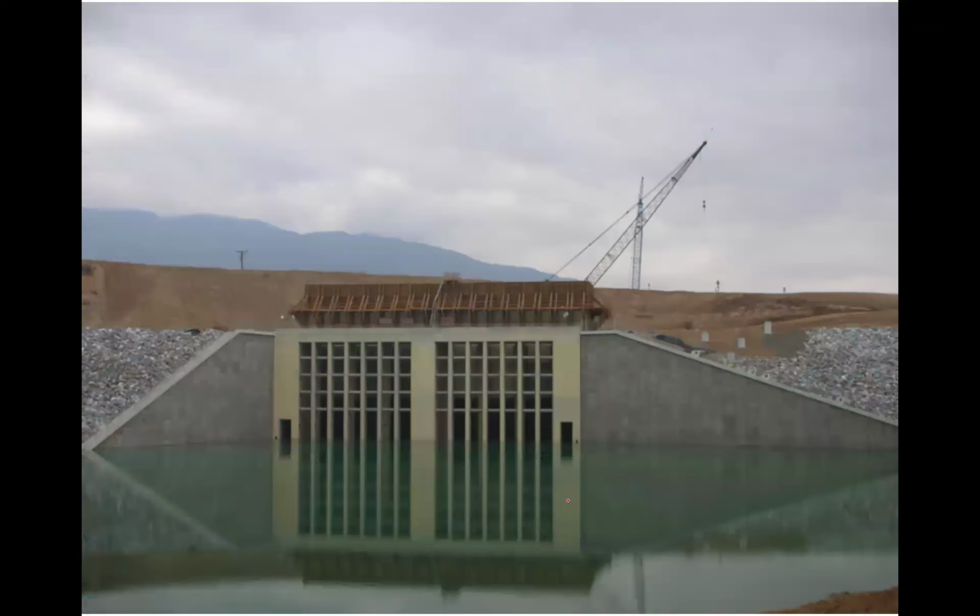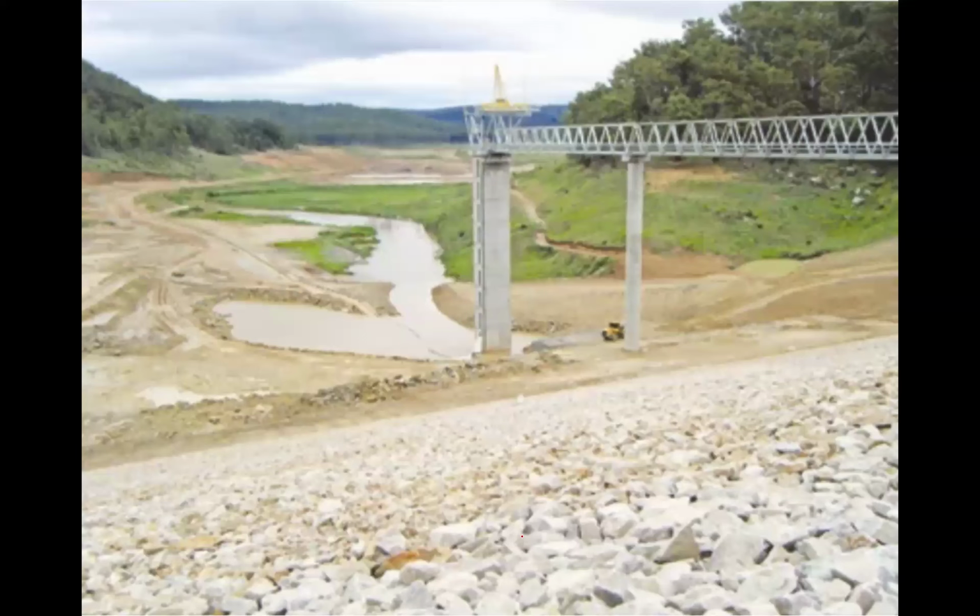This is another one with a zoomed in view with the bigger trash racks, quite obvious. This one's not operating, or I think it's during construction or something, but that tower in the middle is the intake tower, and they have intakes at different elevations. And as you can imagine, when this reservoir fills up later in future, you will have different heads at different elevations, and that will give you different discharges. So you can have, again, some options, some flexibility in how you're withdrawing from the reservoir.